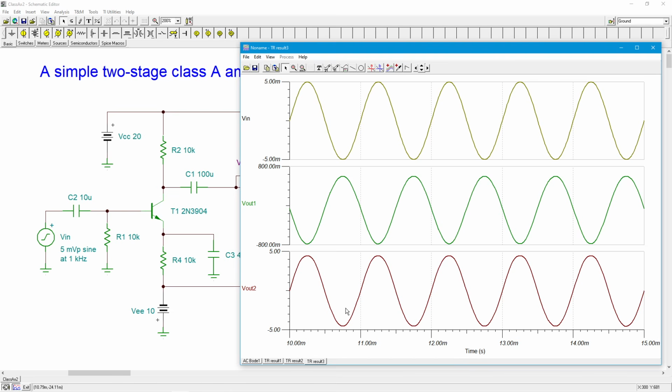So now the same thing kind of happens in mirror image, right? So here's the part that was kind of pointy, and it's now, because it's small, the low amplitude version, right? It's negative 800 millivolts rather than like positive 800 millivolts. That is going to get the small gain. That's going to wind up getting kind of squished, which is this peak right here. Meanwhile, the fattened peak up here, that's the big gain, right? So that's going to get kind of pointy and flipped upside down. So you're going to take the squished part and make it more pointy. You're going to boost it up. And then the pointy one, you're going to kind of squish. And they kind of cancel out.